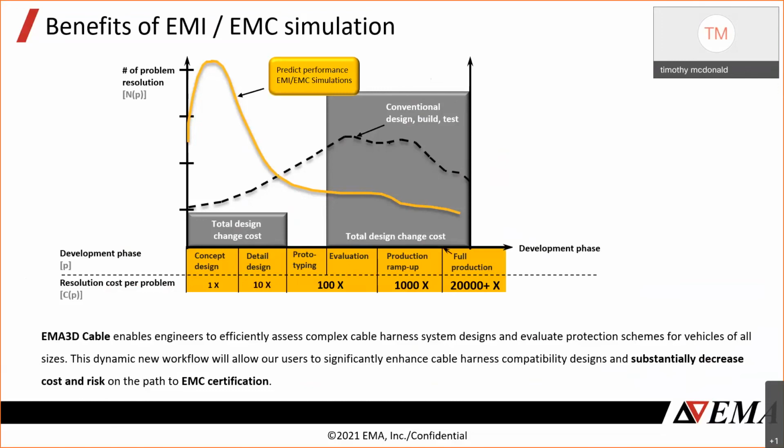For other types, you can use the Electronics Desktop suite to import the ECAD, which basically handles all popular formats, and export them directly into SpaceClaim. So depending on your particular workflow, there's a couple different ways you may want to work with that ECAD, but they are supported.